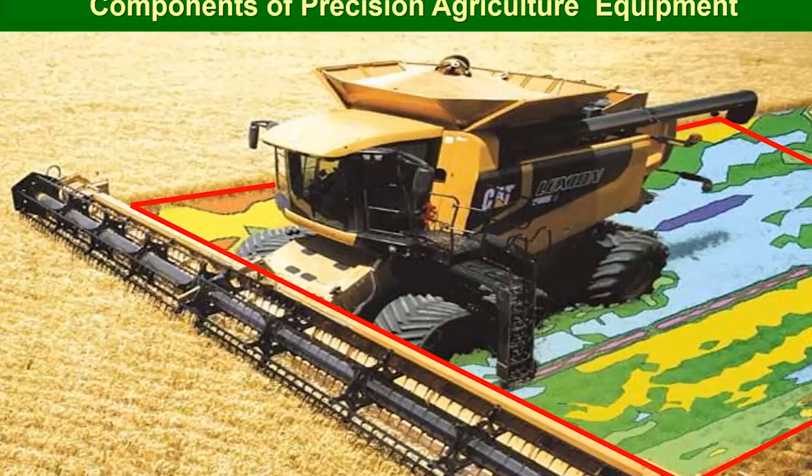Based on the frequency of our reading, you don't need to move this long distance to get the yield data or number. Based on the frequency, sometimes we can adjust it to collect, let's say, 100 readings per second, but it would make an average of every 2 seconds, and send the signal that was the number for these 2 seconds. We can adjust that to make it accurate.